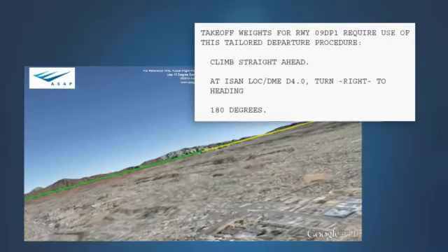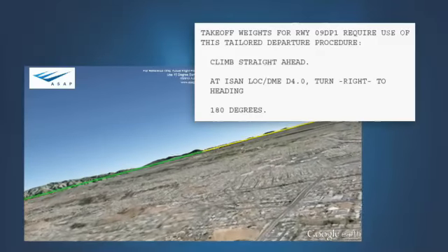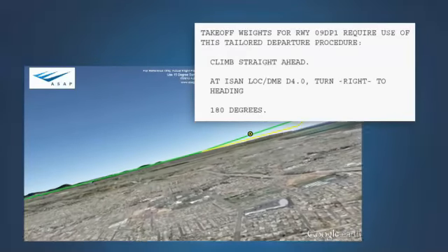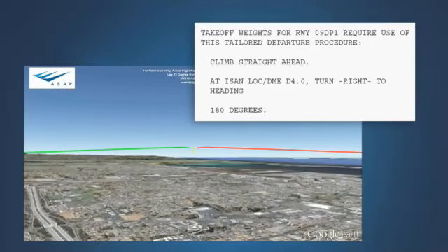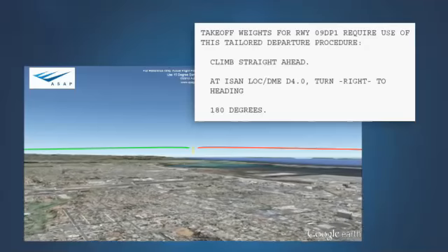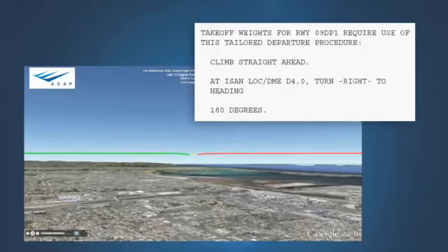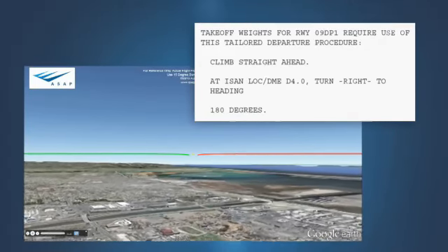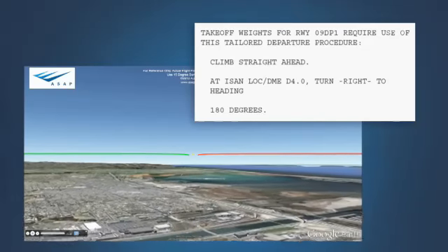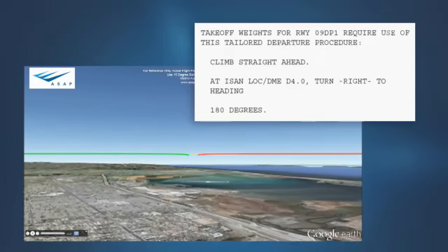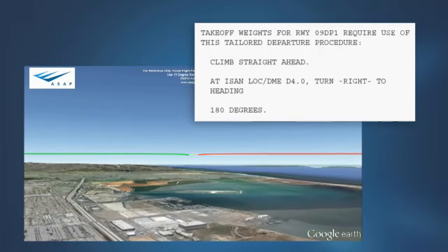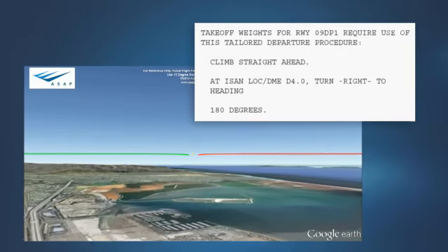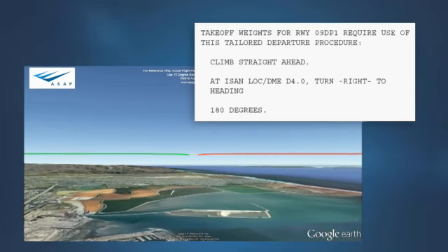The effect on climb performance resulting from the bank angle flown during the turns is included in the allowable takeoff weight limit. Because a turn is involved, the obstacle accountability area expands in width to 3,000 feet either side of the track. The procedure may be defined in simple terms of turns and headings to fly following an engine failure. Ground-based nav aids are usually used to identify the point at which a turn is to begin. Oftentimes, it is beneficial for the engine failure procedure to coincide with the IFR departure procedure used for that runway.